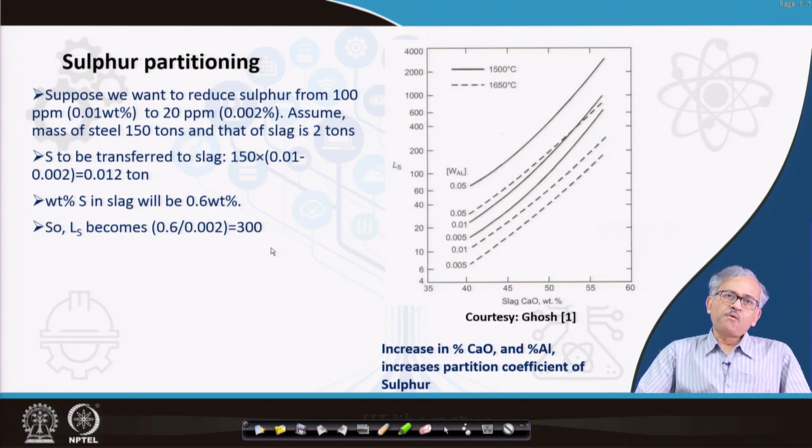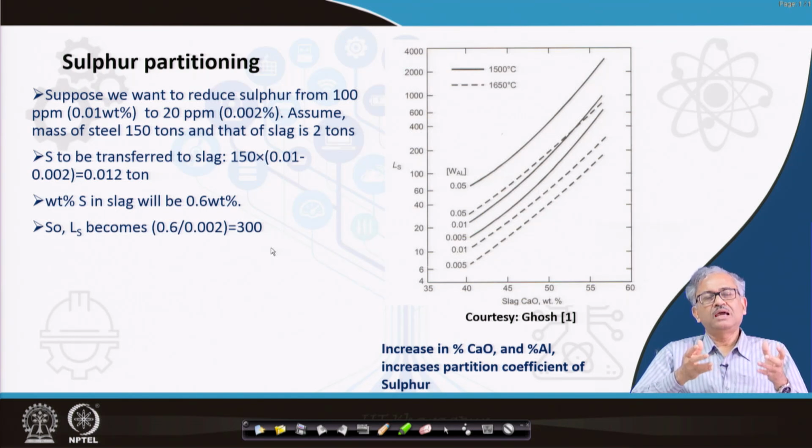The transfer of species from the bulk to the reaction interface is very important. By gas stirring you cannot ensure that it will be completely a CSTR. It will not be an ideal continuous stirred reactor. A CSTR is an ideal reactor, as you may know, and in that case, if you add some tracer instantaneously, it mixes everywhere and becomes the average concentration instantaneously, so kinetics does not have any limitation.